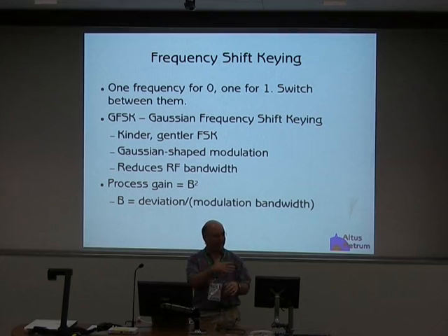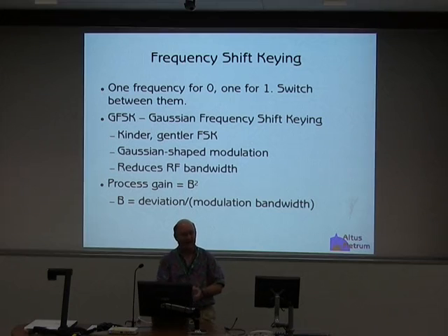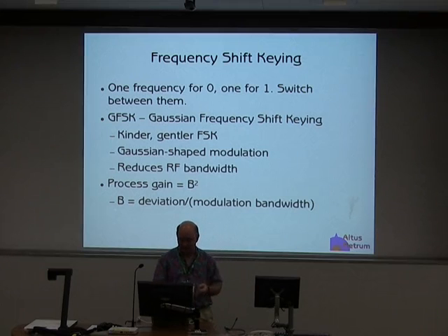The reason that preemphasis is getting you better process gain is those high frequencies are very hard to encode. And so by amplifying those high frequencies, you're getting more process gain for the high frequencies of your regular FM signal. So that's why preemphasis in the FM environment exists. And that's why you hear hiss on an FM radio, because for exactly the inverse reason, the high frequency noise is being amplified because your process gain for that area is actually less than unity. And so you get a bunch of noise coming into the system.